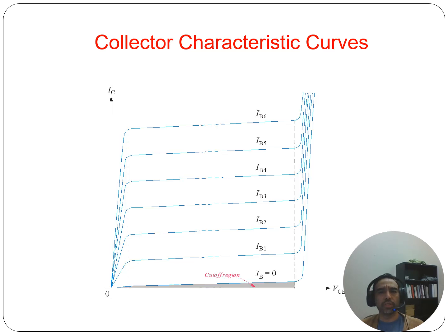So we said collector characteristic curves, plural. What are collector characteristic curves? In the graph, the curves show how the current through the collector, I sub C, changes with collector emitter voltage, VCE, for different base currents, I sub B. You can generate this graph with a transistor if you have the right type of device. We used to have a transistor mapping device that would calculate these characteristic curves. You just stick the transistor into the circuit already built into the device, and it would run different base currents and give you the characteristic curves.